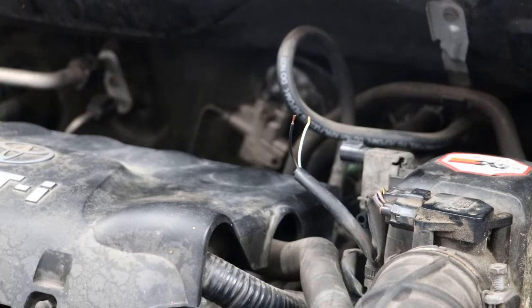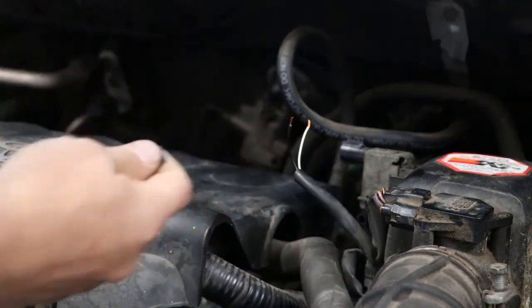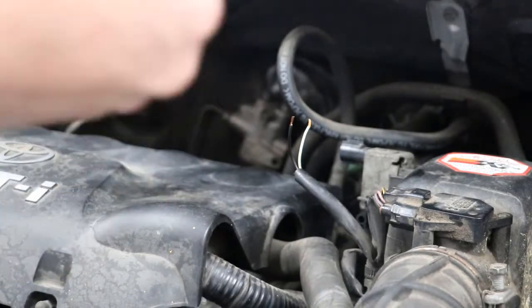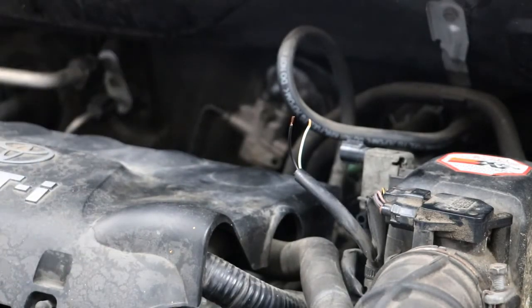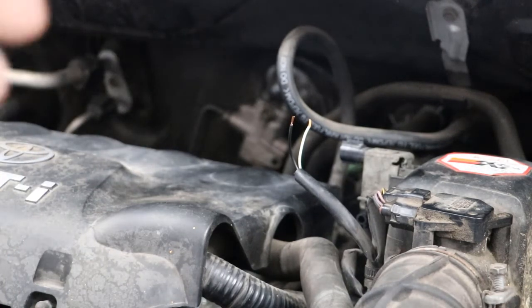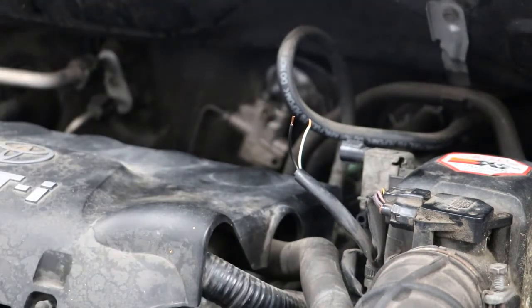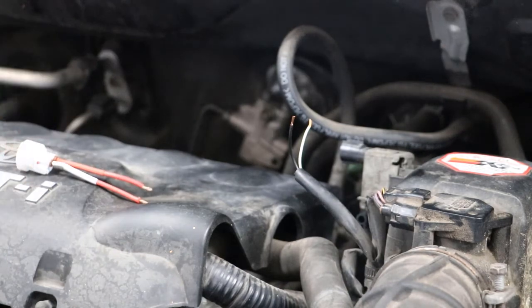So guys, all I was doing over here, sorry, was cutting my large shrink wrap to go over all of this, plus have a little bit of additional, since I'm going to move it down, and an individual shrink wrap for each of the wires inside of this, so that they're protected inside the shrink wrap and not touching each other. Technically I could just do one, but I prefer to do both just to be on the safe side. So what we're going to do is slide on the very large shrink wrap here.